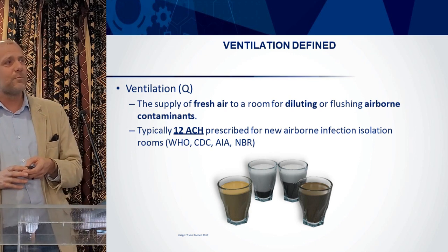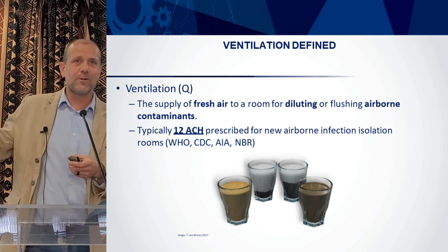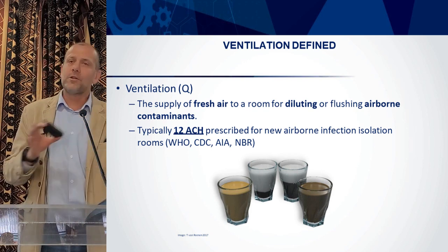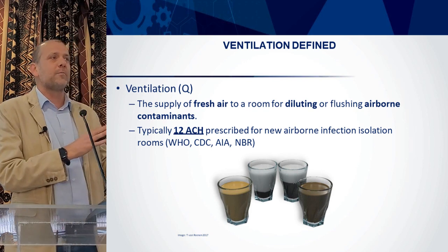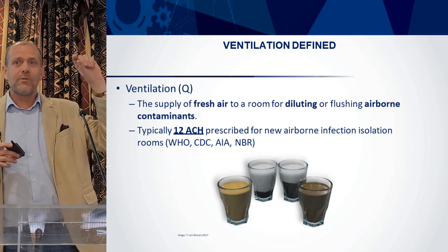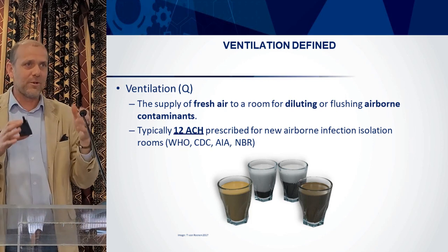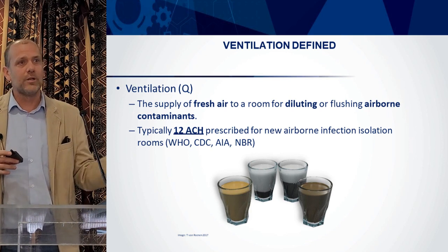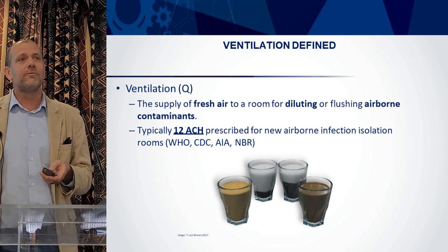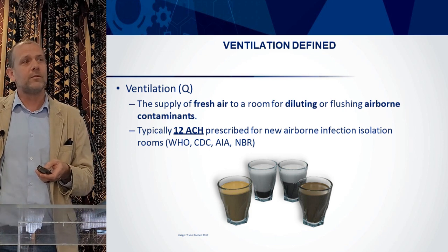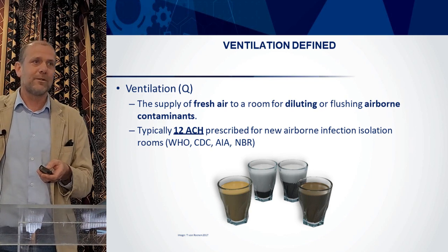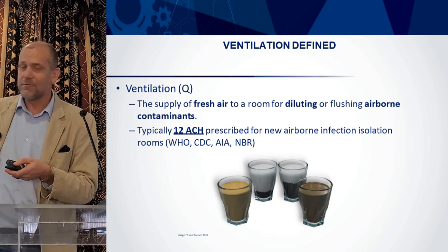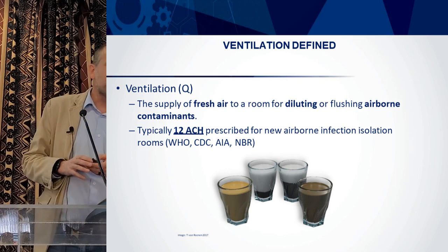And apologies to the coffee lovers in the room, because in this context, coffee is the contaminant and milk is the dilutant. If you look at the two coffee cups on your left, look at the rate of coffee production in that room, the glass, versus the rate of fresh air production, the milk. You get a more dilute condition. If you've got a higher rate of contaminant production to the dilutant, your fresh air, you get a higher concentration. If you like coffee, you like the stronger stuff, so maybe not a very good example.